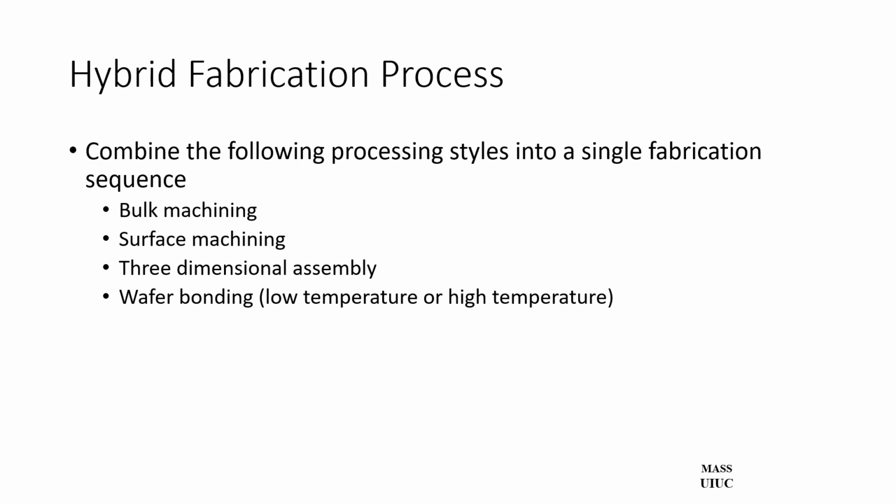People need to be able to choose hybrid processing where bulk micromachining, surface micromachining, three-dimensional assembly, and wafer bonding are all mixed together for the interest of the best product. And a good MEMS designer should be able to understand all these different categories of processing capabilities.